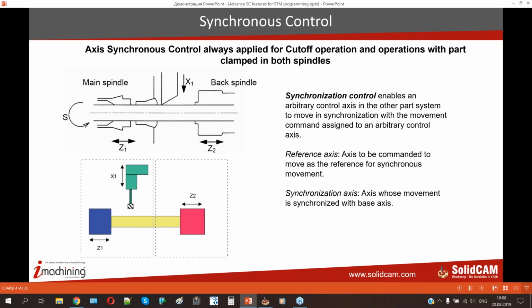As I said, you can't have two Z-axis movements in one line of the code, but in terms of the machining process on a Swiss type machine, you need your Z2 sub-spindle axis to support stock, which is moving by the Z-axis too. And in means of such control, you should choose which axis will be leading and which will synchronously follow it.